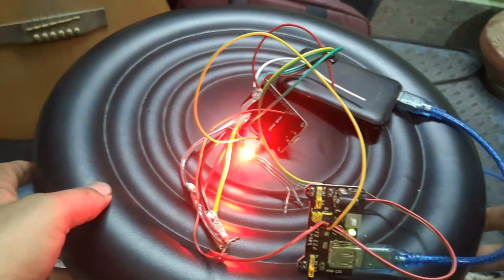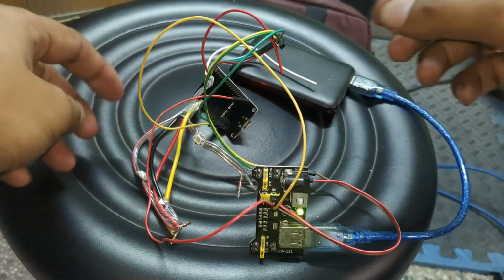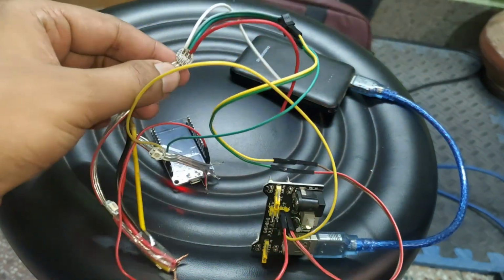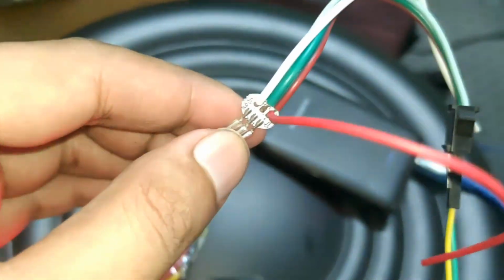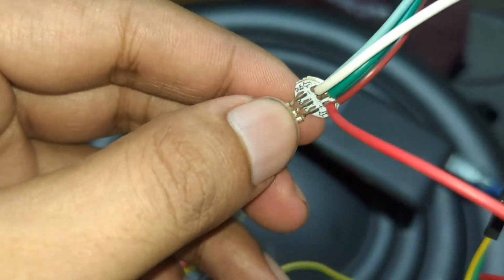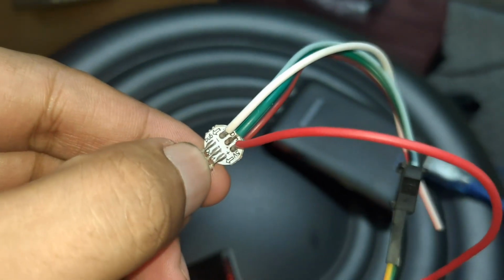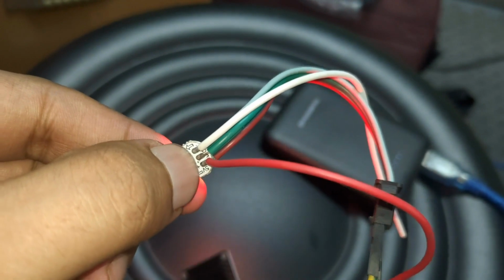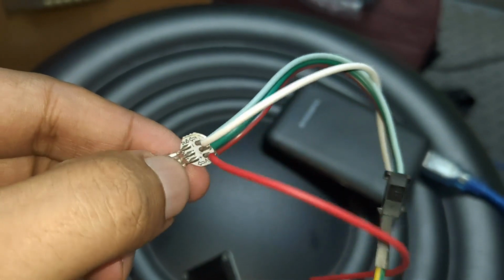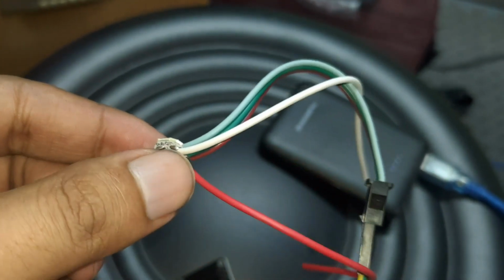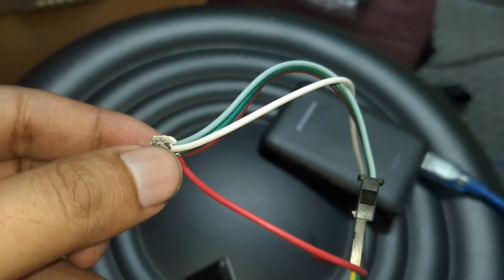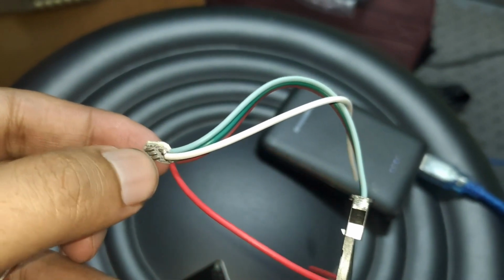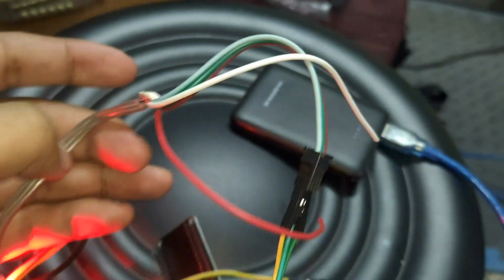If you want to see the LED enclosure, let me just see. Okay, I think that should be fine. So if you can see, this is the inputs it has. It takes 5 volts here, then this is the data pin, and this is the ground wire. So it will flow like this. You need to provide power on this cable on the first LED, and the data cable, and then the ground, and it is going to pass all those inputs to the next LEDs.